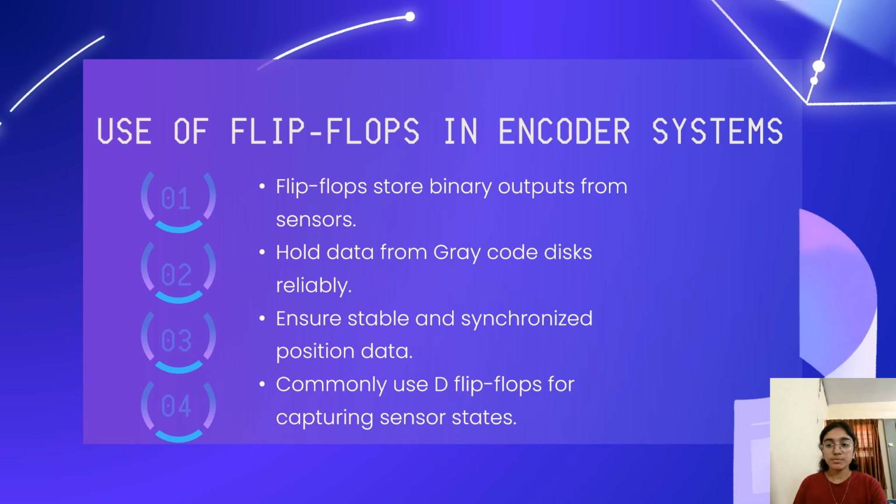Here, flip-flops act like memory units. They store the sensor outputs so that the system can read them reliably. D flip-flops are commonly used because they easily capture and hold the sensor data at each movement. This ensures that fast movements are captured properly without glitches.